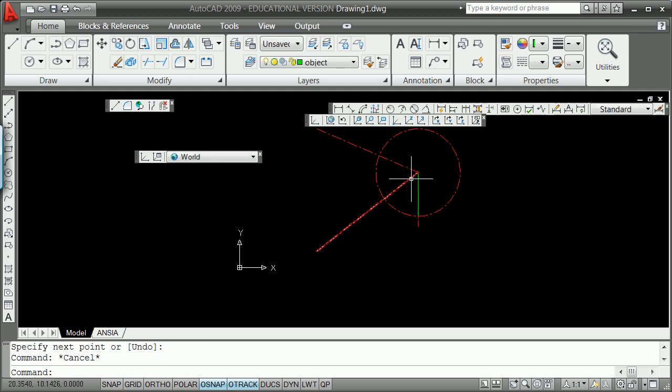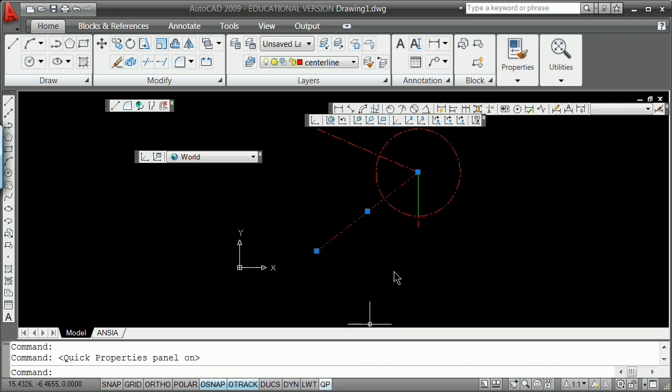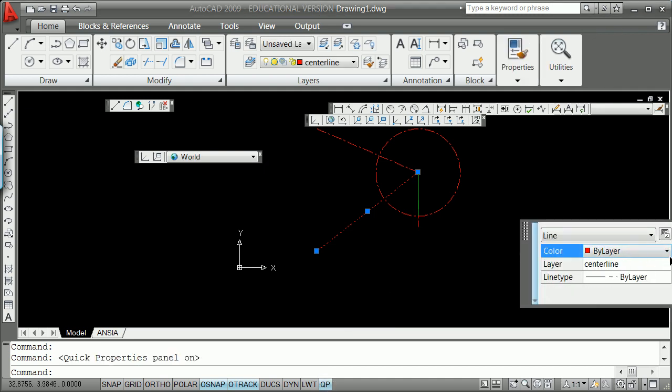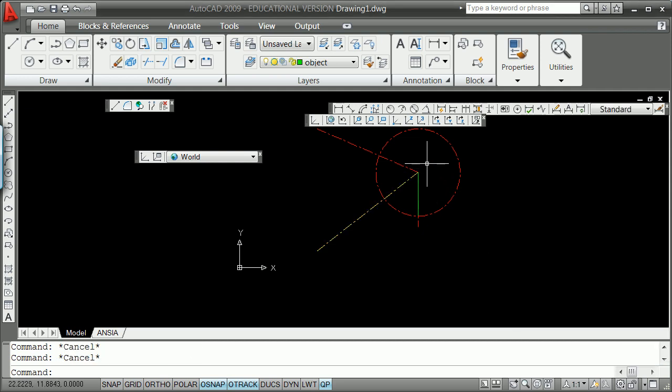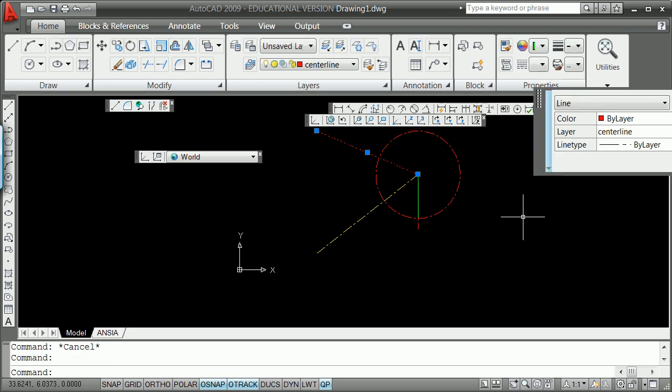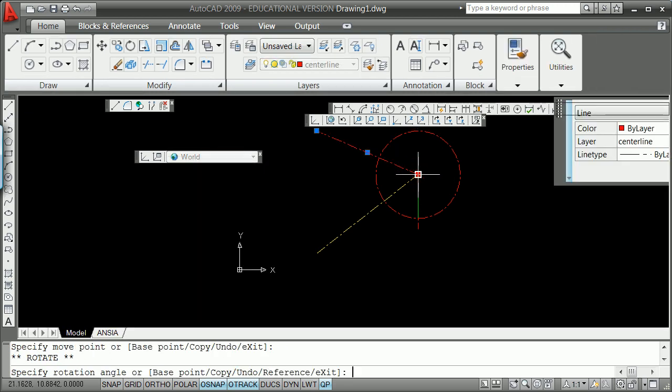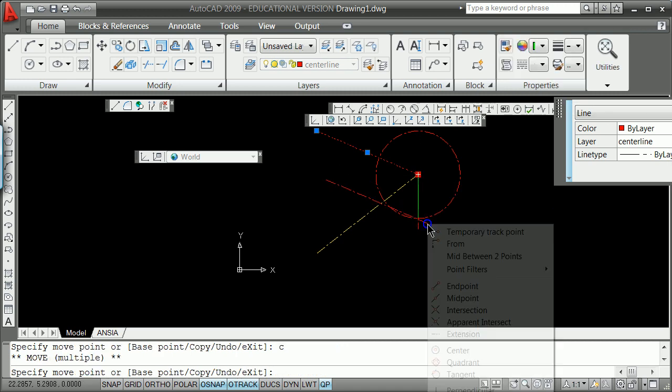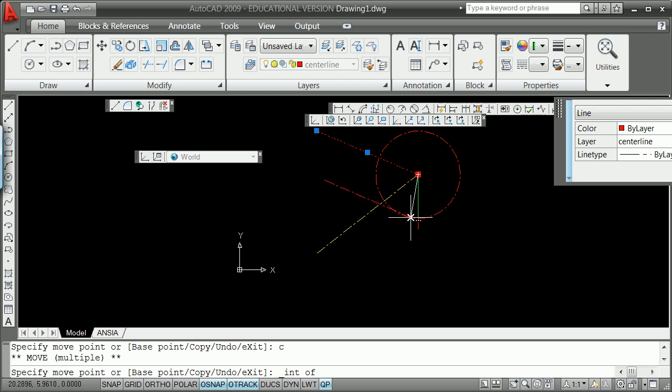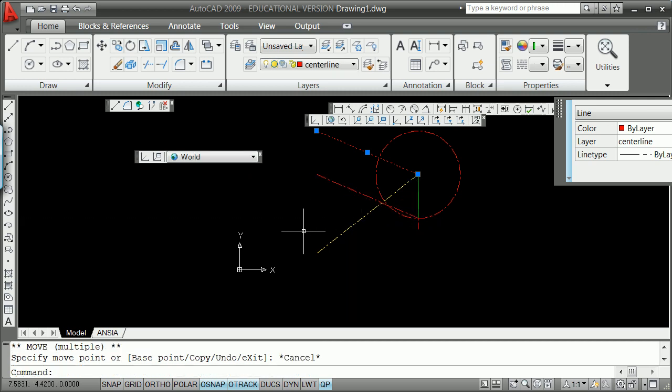Alright, you got to go back to there along 2 routes. You do that by offsetting. You decide you're going to go back along that route. Maybe it's not a bad idea to use one of the rules you never get to use, quick property, change that color all of a sudden because you're going to use it as your route home. I don't know, is yellow the route home? And then not a bad idea to learn how to copy parallel, so you can go to other programs. So I left click, spacebar, C for copy, shift right click the intersection here. Now I can trim.